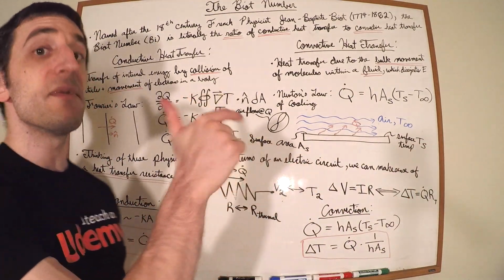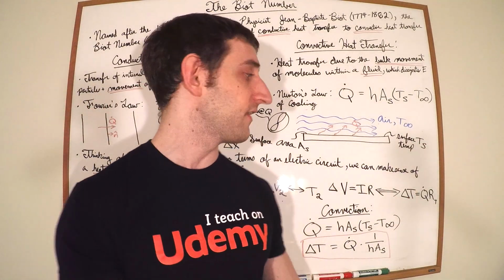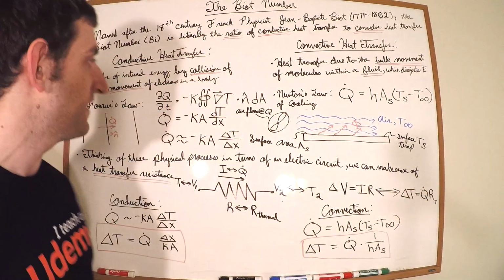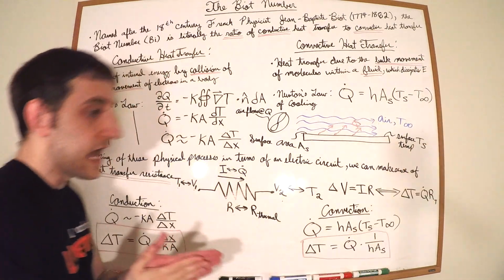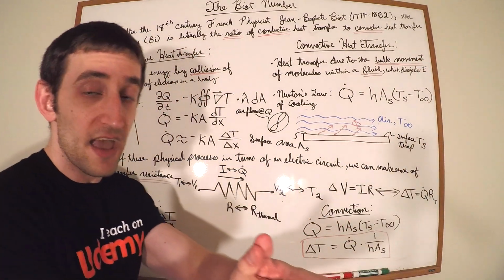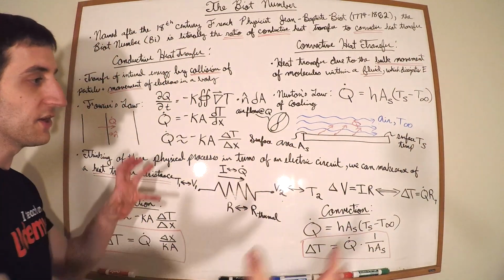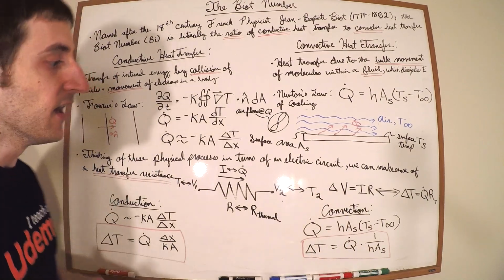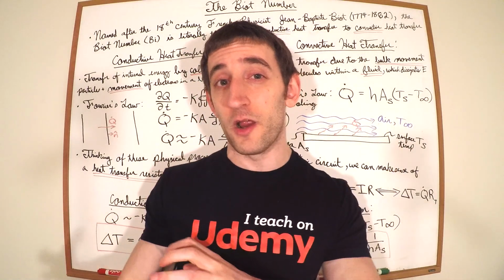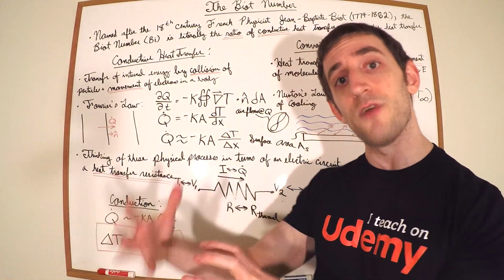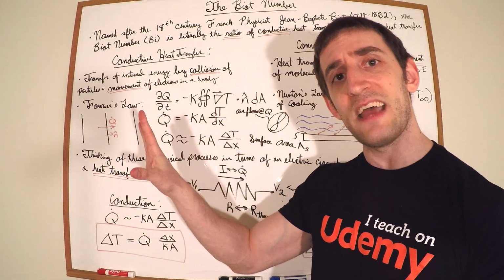You can do the same exact thing in heat transfer analyses, where you might have heat transfer through this wall, you might have convective heat transfer, and maybe it goes down this path, the energy, or another path, and you can reduce it down to an equivalent resistance. That's what's done in a lot of engineering. We're going to take more of a physicsy approach where we take the equations of motion and derive the temperature distribution, but we'll get to that shortly.